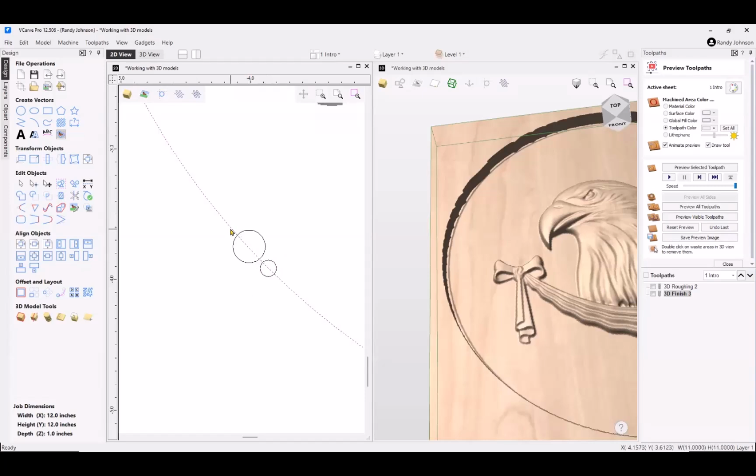So if you had a very precise circle that you were trying to cut, you actually have to make that circle smaller by at least the radius of your largest bit, because it's going to cut to that direction. So that's what's happening in these 2 setups here. That's why you have this rough edge, and then the 1/8 inch coming in and just coming up to it.